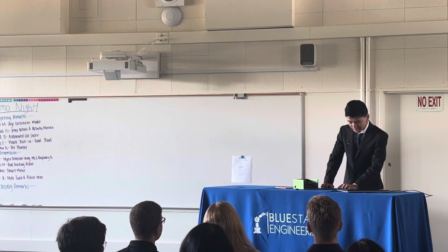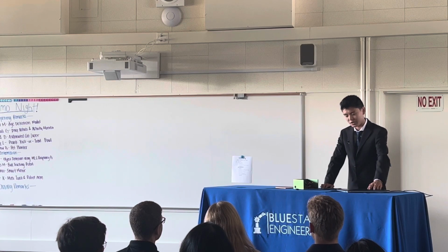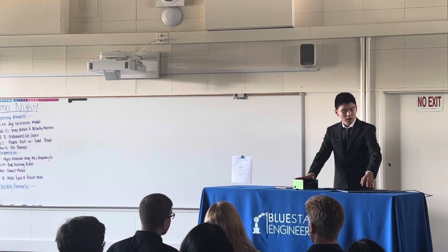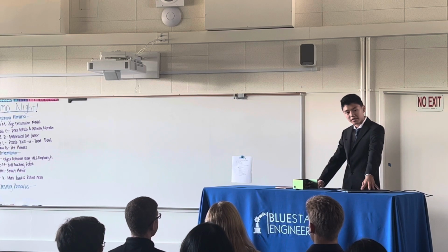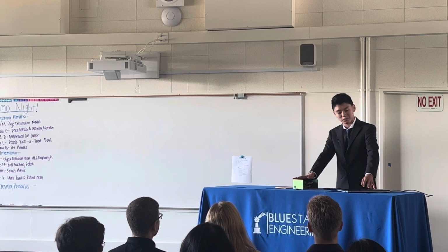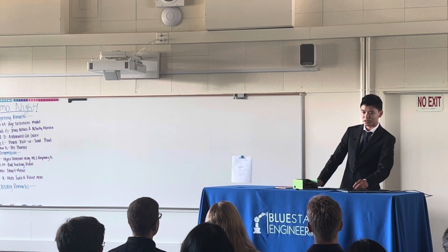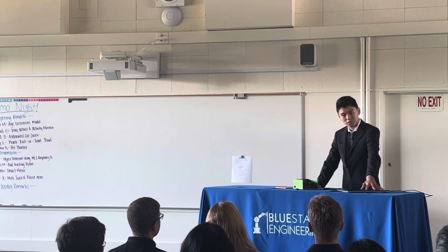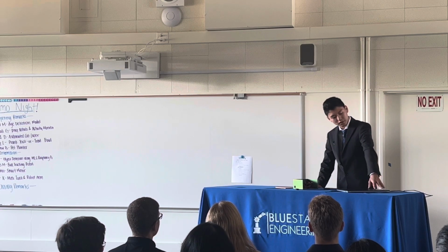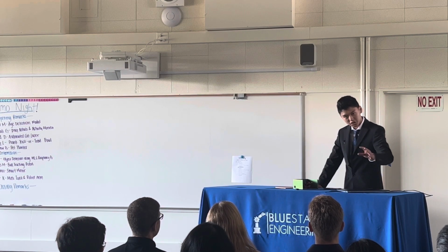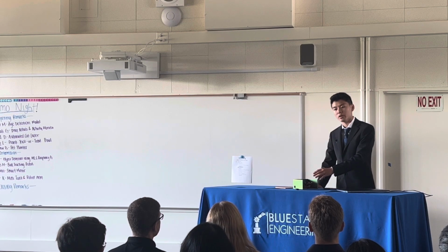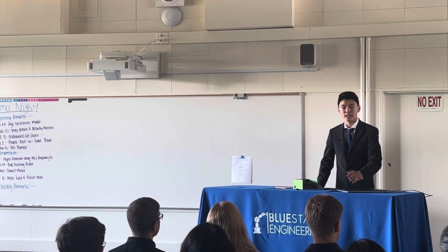A big problem I faced with this project was establishing communication between YOLO V5 and my Arduino board, because YOLO V5 is in Python while the Arduino board is in C++, two very different languages. In order to establish communication between the two, I have to go into the detection program and encode specific information into either bytes or strings, and then I can send it to the Arduino board in a way that the Arduino board can understand.